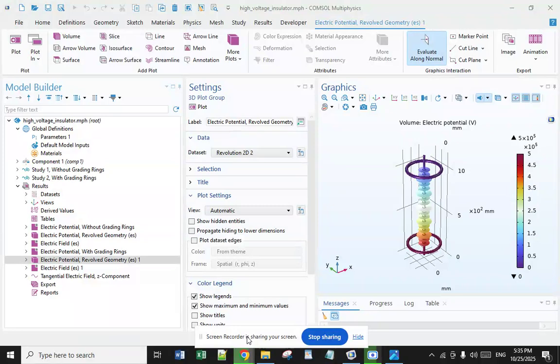Among the most significant are materials and design. The materials used in the manufacture of insulators, as well as their design, are key determinants of their performance. Porcelains and glass have traditionally been the most commonly used materials, although in recent decades polymer composites have gained popularity due to their resistance to contamination and lighter weight. Proper design is also crucial to maximize insulation capacity and minimize the effects of surface contamination.